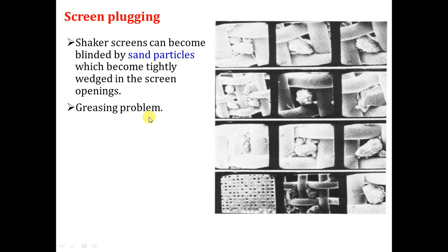A lot of the lubricant will become grease on the shaker, and it will cause plugging or blinding of the screen. So you have to reduce the calcium and use the wash gun in order to avoid this problem, because the greasing problem can damage the screen so it cannot be used again, and it can also lead to a lot of mud losses or overflow from the shakers.